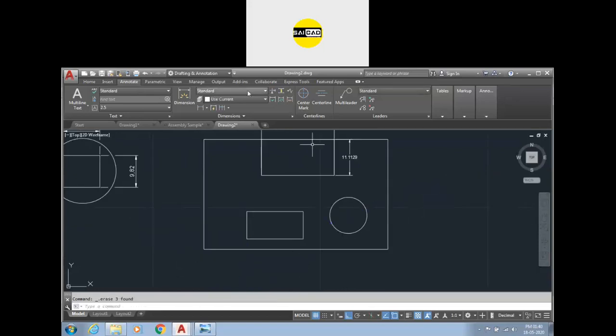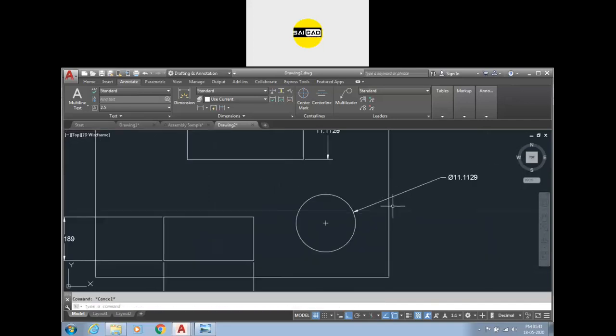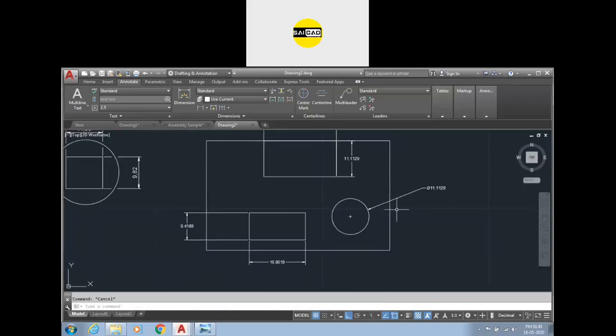So I'm going to create some dimension again. I'm going to show you again how we can create some breaks. So here we have some dimensions like that. So we know that the dimension line should not cross the geometry line. So you can just go to the break here and select the dimension. If you want multiple, you can select the multiple dimensions you want to break. Okay, press enter.